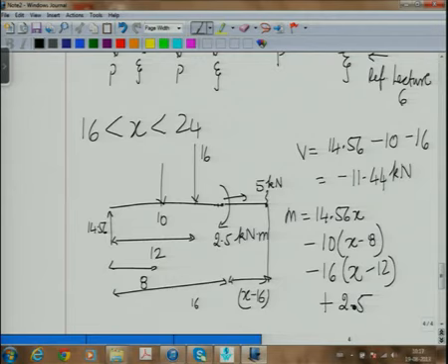A clockwise moment induces a positive bending moment on all sections to its right. And I also said it does not explicitly do anything to the shear force. So this 2.5 kilonewton meters did not affect the way we wrote the shear force equations. We only put forces.